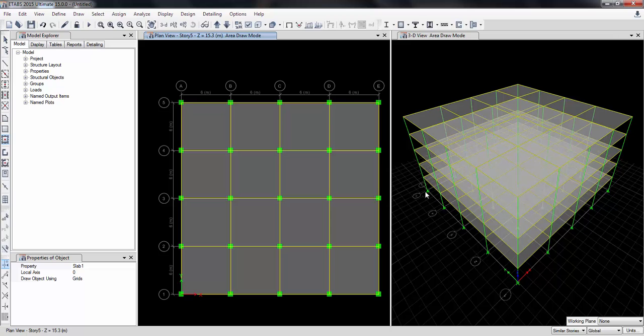It is required different reinforcement details, and the pin jointed footings should be designed separately. So we will keep it for fixed design, for simple tutorial, for making it a simple tutorial for you. I am keeping it as the bottom footings. I am keeping it as fixed support.